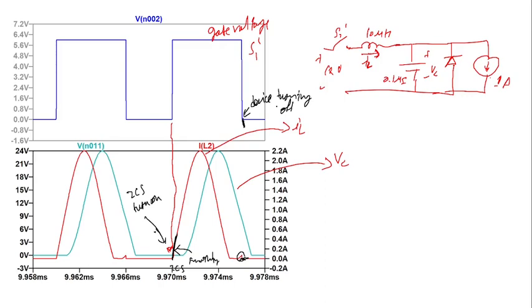So ultimately what I'm trying to say here is, when you are giving the pulses for turning off, before turning off the device, the current is automatically not in the device, but it is with the capacitor only. So that is the reason you can see this is the ZCS turn off. I hope you understand how the ZCS turn on happens at the start of the device, and how the ZCS turn off happens with the device.